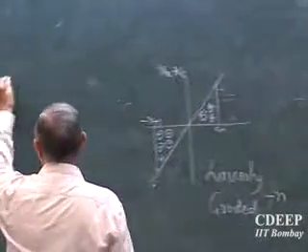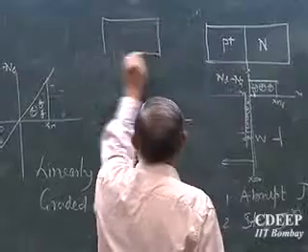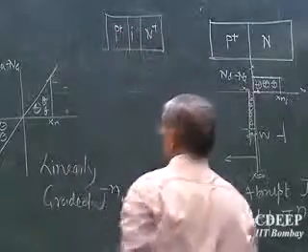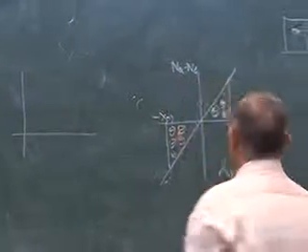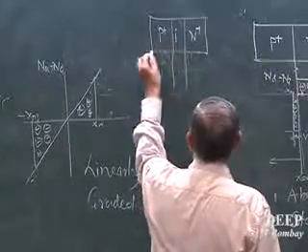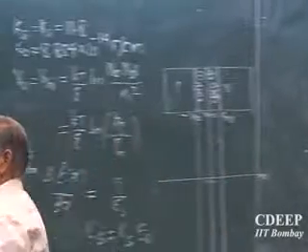The third possibility, or many of them in fact, you may have a diode which is called, I don't know whether you heard of this diode any time, but hopefully yes, a PIN diode. P-I-N. I think in this course I may not show you, but what happens if this I is intrinsic, this is called a hyper abrupt junction. The I can be smaller and I can mix both N and P grading, and then I can create another junction which is called a hyper abrupt junction.